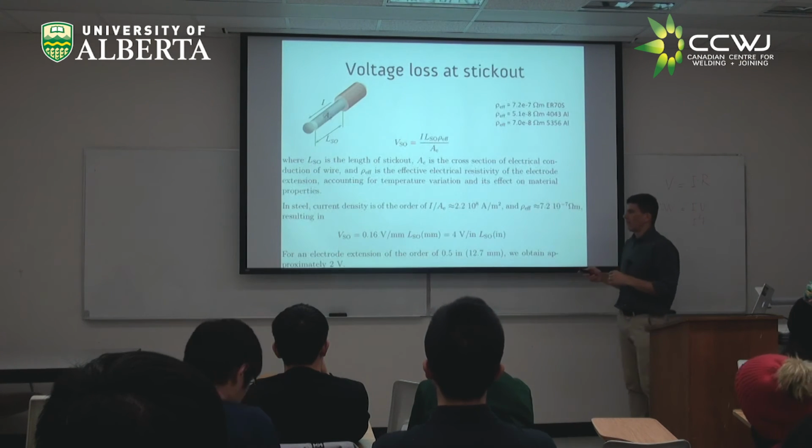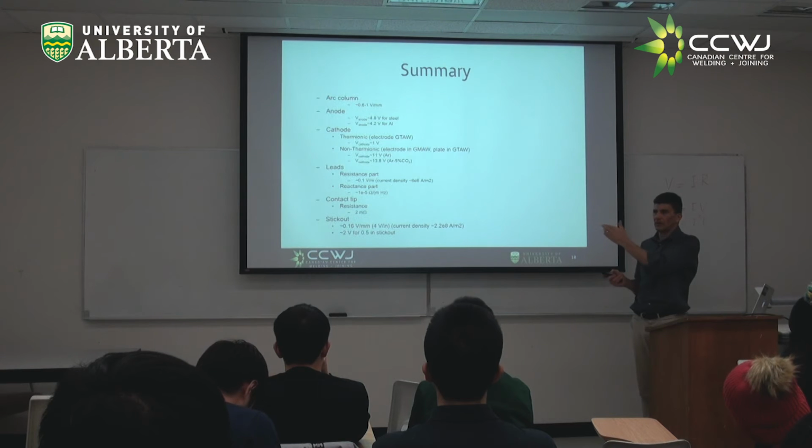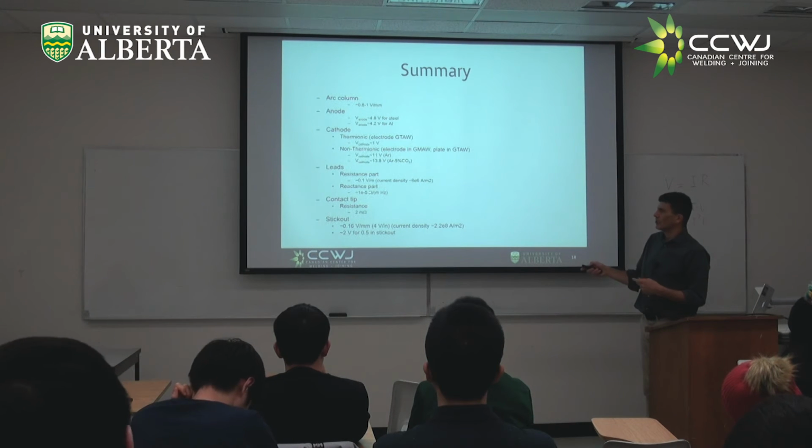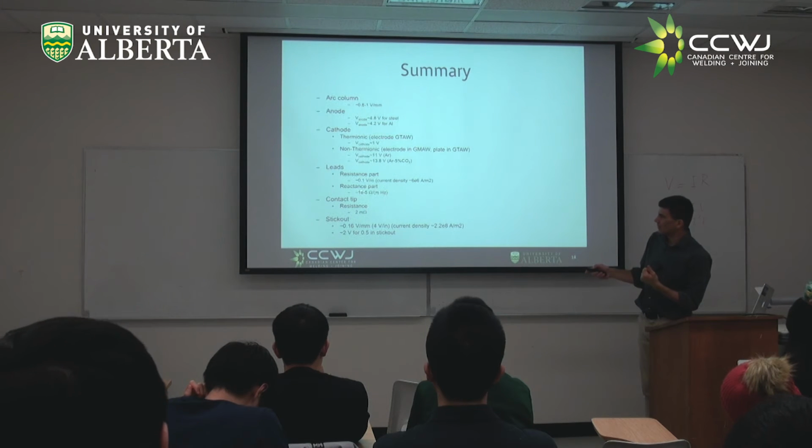So this is just a rule of thumb. If I don't tell you anything, you can use this, which will be tabulated. And if I ask you to calculate it, you would have the formulas to calculate it. But this is the way of calculating your reactance. You multiply by the length of the lead. This is per meter of leads, right? We're talking about the leads.